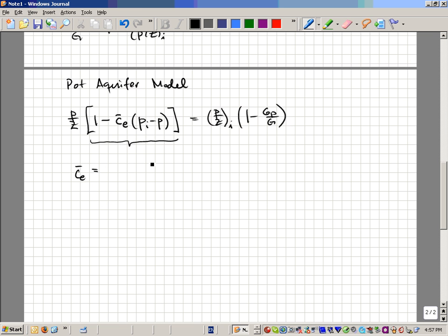In the early 1990s, this is equal to the formation rock compressibility plus the water compressibility times the connate water saturation plus a term M, and this is related mainly to the aquifer volume size. We'll talk about that. C of F plus C of W, total compressibility of aquifer, divided by 1 minus connate water. So typically we might have something in the range of 25% connate water.